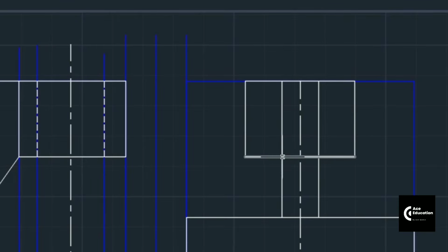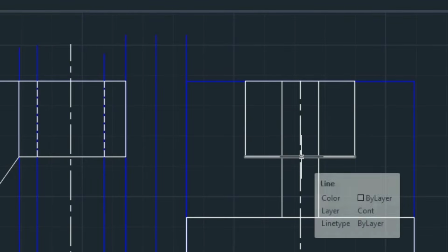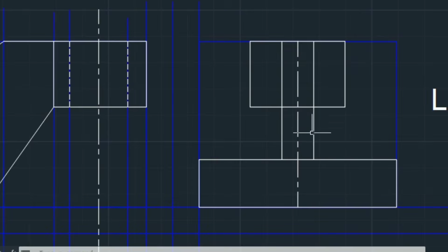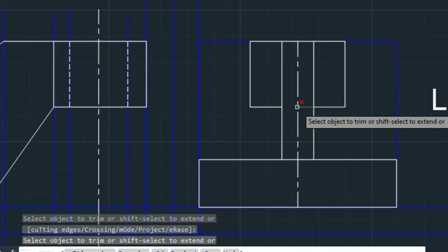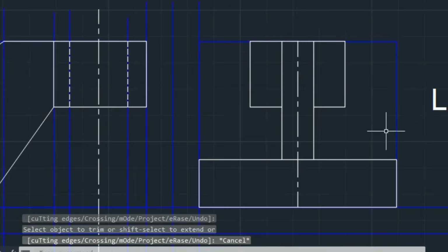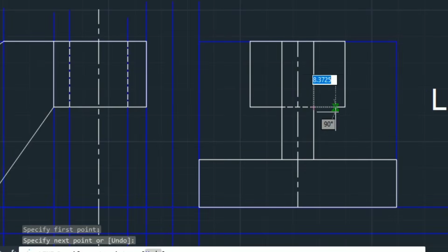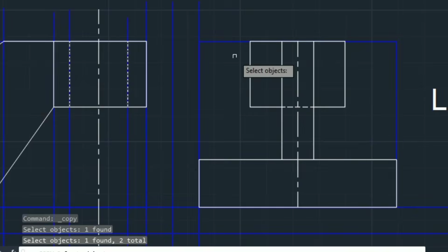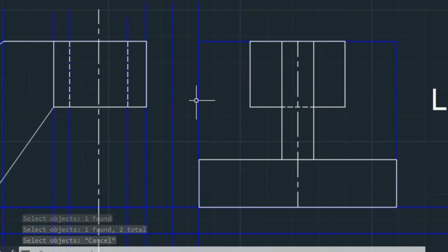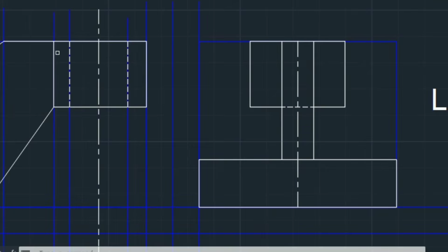If you see here, the part of the circle cannot be seen because the 12 mm thickness plate comes first, then the cylinder would be there. That's why this edge of the cylinder should be removed. But there you can show the hidden line. Now here I want to draw hidden lines for the circular hole, the way you have just drawn in the front view.